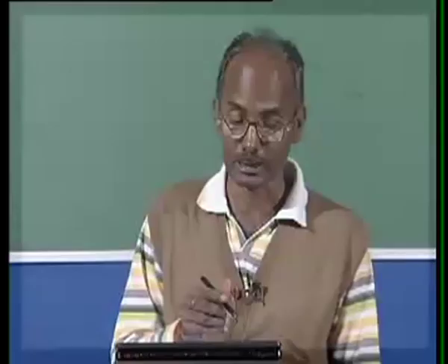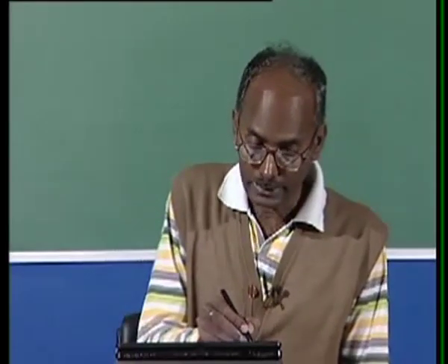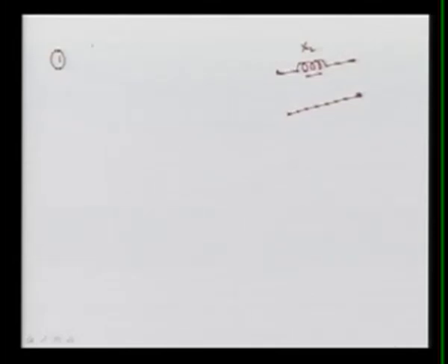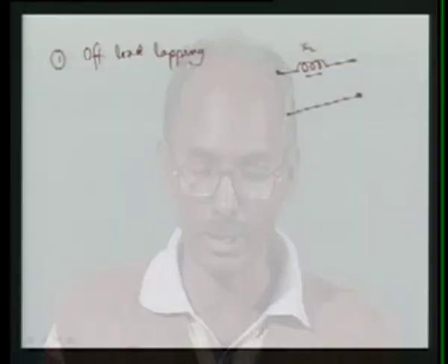Now the transformers again can be of different types. As I said, we can have some transformers with tap changing positions. It is called, let's suppose, an off load tapping transformer. Normally some transformers are provided with some tappings. Whenever the voltage is going to be less or higher, we can change the tappings and then increase the voltage. So what we are doing with the changing of the tapping is nothing but trying to provide some reactive power.